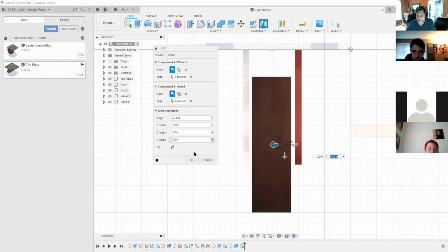So it's 0.2. Well, we know, and if we do the calculator math here, you can't see the giant calculator on my screen, but I've got a calculator up. 1.125 was the opening of the outside. We know that each one of the thicknesses of the arms are 0.125 or 1/8 of an inch. So we're going to subtract 0.25.